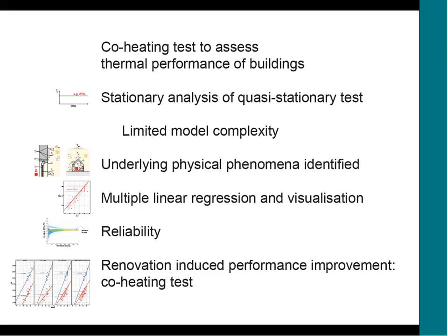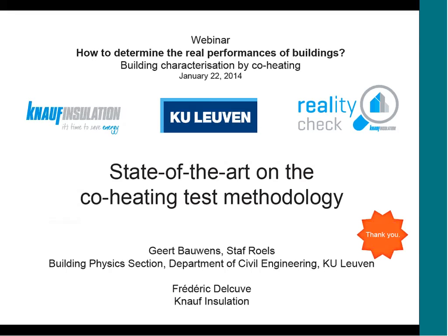We've also talked shortly on the reliability of the coheating test, where we saw that given the right assumptions and sufficient duration of the experiment, we can be confident that we will obtain a reliable result. And we've also shown that the coheating test is a nice way to show the renovation-induced performance improvement of the heat loss coefficient.